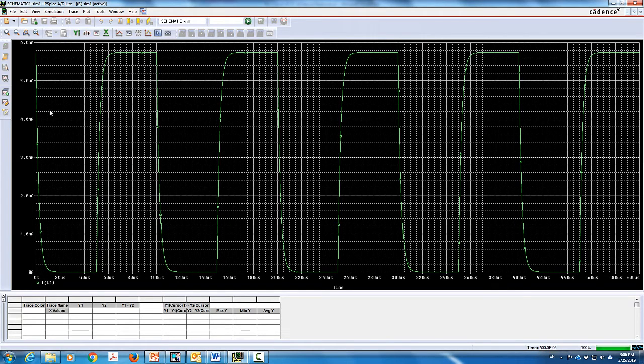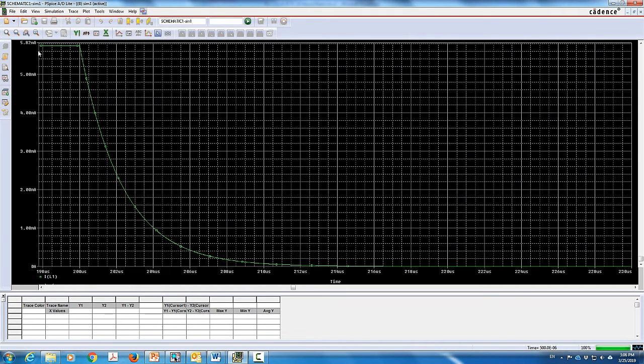And this will happen every time we go through the pulse, every time we turn off the pulse. So this is a very good way to mimic the source-free circuit. Basically you want to look at the response of the circuit after removing the voltage source. And this basically is going to be in this area over here. Right, so you can see that you have a constant current until we turn off the switch, and then the current through the inductor will exponentially decay as shown here.